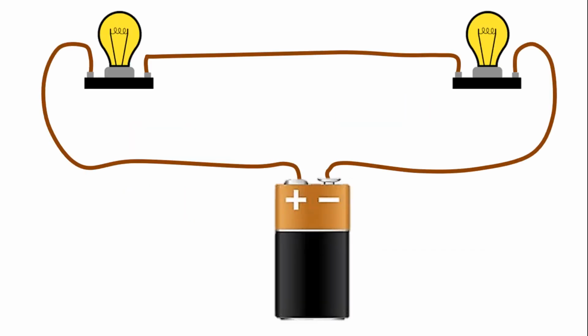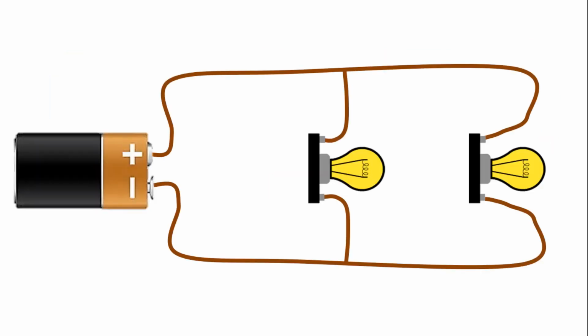Since the same current flows through all lamps in series-connected lamps, when one of them explodes, the other does not light. Because the place where the exploding lamp is will be an open circuit, no current will flow through the other. Here, the solution is parallel connection. But it is not so with parallel connected lamps. Since all lamps have the same voltage, even if one of them explodes, the other continues to burn. Here, we have given an example of a lamp as a load. It can be any circuit element instead of the lamp.